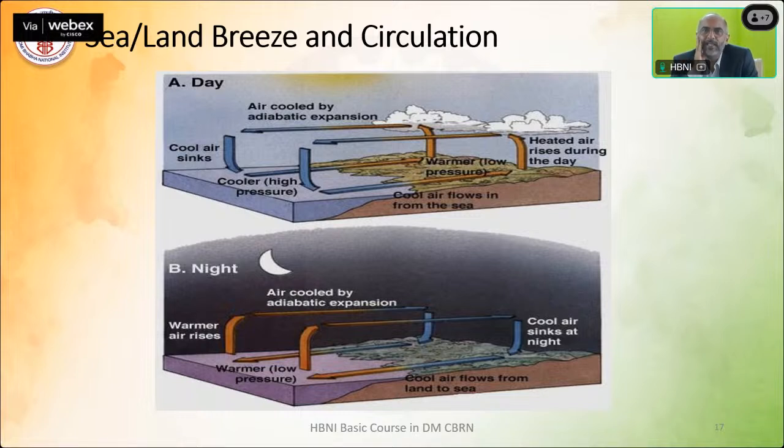So I was again explaining some basics of dispersion modeling. The very basic thing that influences the modeling is the atmospheric stability classes, and how the wind behaves in day or night time. It is all about the lapse rates, the differences between the atmospheric lapse rate and the adiabatic lapse rate.